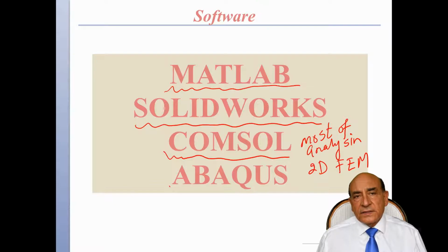That is a very good platform to solve partial differential equations that describe elasticity, heat transfer, fluid mechanics, all kinds of physics, continuum physics in general. For us, we would just use the structural mechanics module in COMSOL and do the 2D finite element analysis.